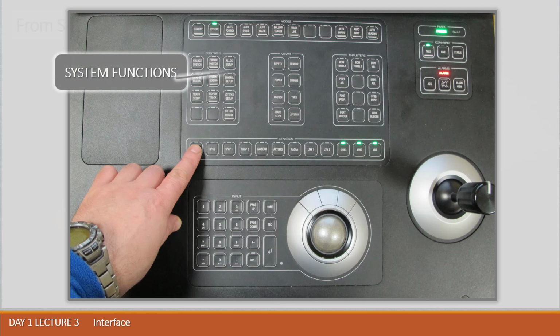Ensure that you are moving with appropriate speed to press those buttons. I mean, the rate of turn should be reduced to minimum, and the speed of movement should be less than half a knot when you are trying to press the present position button.